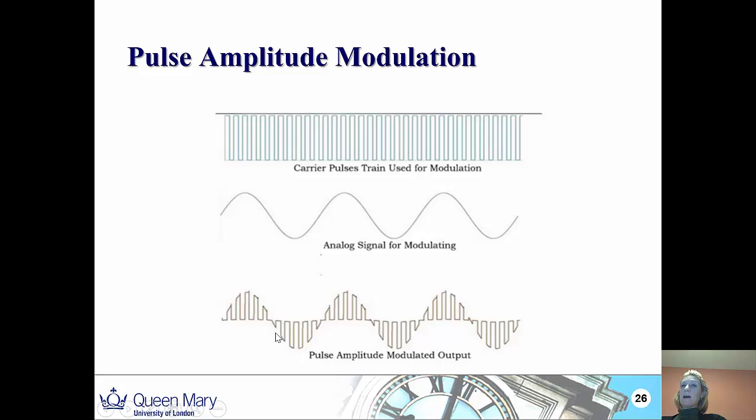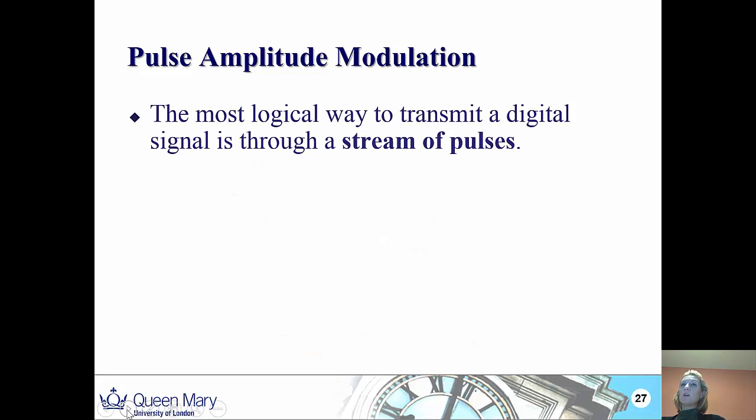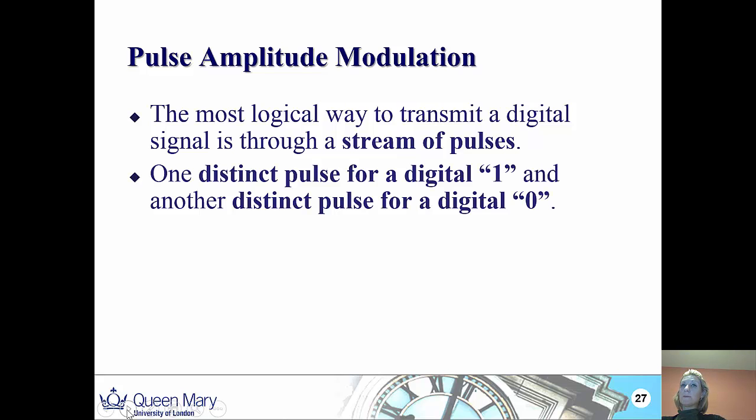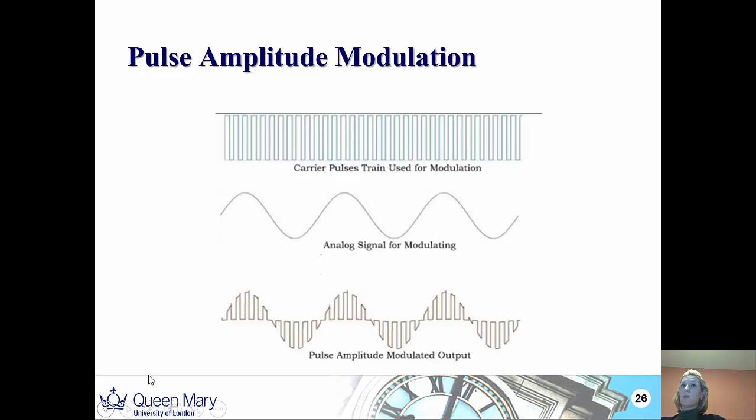So as an example of frequency modulation, we have our carrier wave, which exists between the communicating devices, so the sender and the receiver. We have our signal of information here, the data that we actually wish to communicate. So the logical way is we can apply our signal on top of the carrier wave, modulate the carrier wave so that our information is represented on this wave, and by doing so convey that information to the receiver. So we have here an example of frequency modulation.